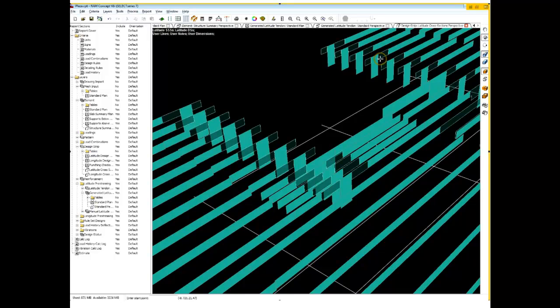If you look across the top, as it's going across, it looks like it's going okay, and then it hits that girder or member framing in, and now you've got this big, huge mass of concrete that it's trying to detect in the cross-section. So I guarantee when we look at that design of the beam that there's going to be something that you just inherently are not going to agree with, and you're going to spend time problem solving it. So just by cleaning it up in this way, you're going to get a much better design.